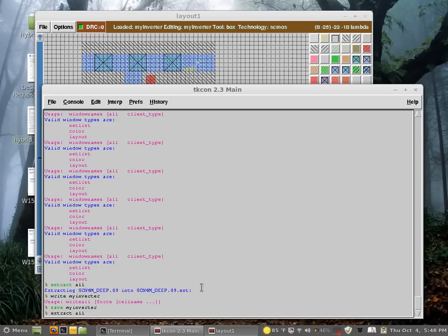By the way, Magic is a little bit, I mean, the whole Unix environment over here is unstable. Your account may become full because of your quota, and if it becomes full, Magic starts to behave strangely, and it would crash, and all your work would be gone. So I very heavily recommend saving a lot and backing up your file. Like every once in a while, if you're working on your project, back it up, put it on a flash drive or something, because this is not a very trustworthy software, and you don't want to start over from scratch.